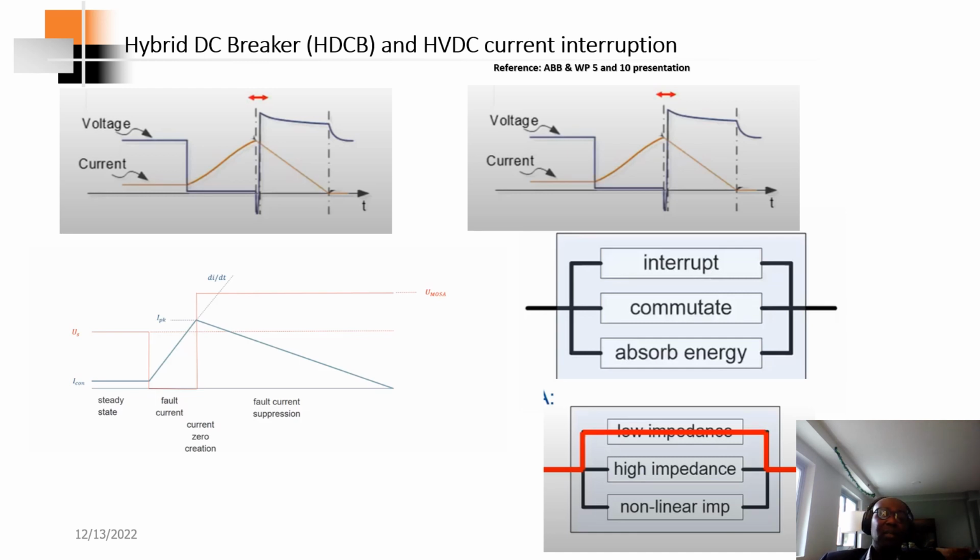As it gets to this part, that is when the counter voltage comes into play. So the circuit breaker creates this counter voltage, and that helps to push the current to a zero crossing where it is interrupted, right? So the goal is to interrupt, and that is the main branch and the auxiliary branch, and this is the main branch, and the metal oxide varistors to absorb the energy.